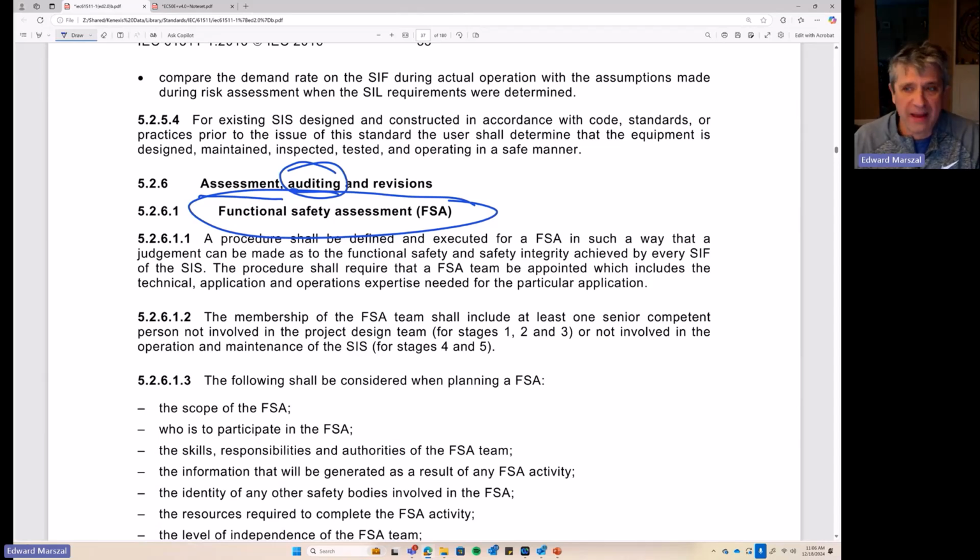As a matter of fact, they will make the real PFD even worse because you have basically given the humans more opportunity to create failures, and those human failures are systematic. So 100% common cause. So instead of trying to bump up your failure rate in your PFD calculations, you need administrative controls. You need planning to make sure everybody knows what they're supposed to do. You need competency to make sure everyone is capable of doing what they've been asked to do.